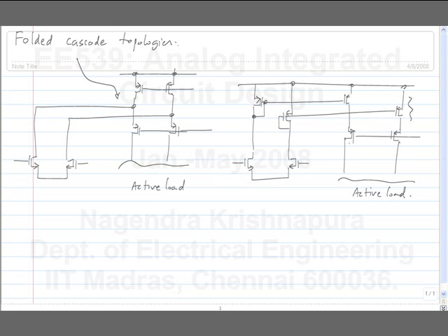What happens at high frequencies because of this node, this particular node? So there will be a parasitic pole. What is the frequency of the parasitic pole? I think this was M7, M8. What is the conductance associated with this node that gives you the pole? gm7, right? It's a common gate amplifier, so it will be gm7. And what is the total capacitance here?